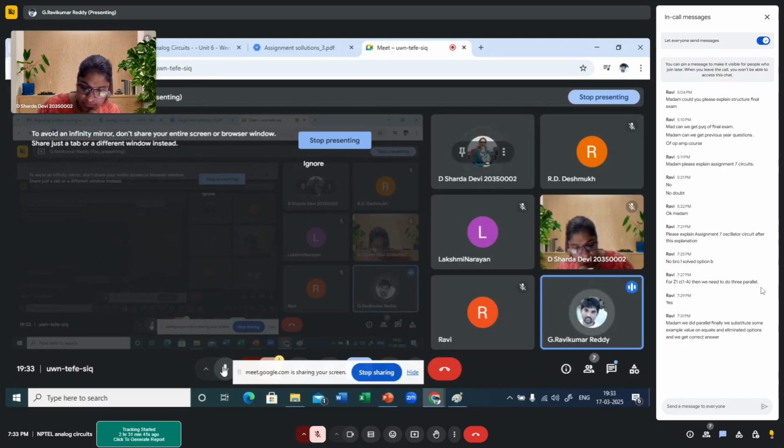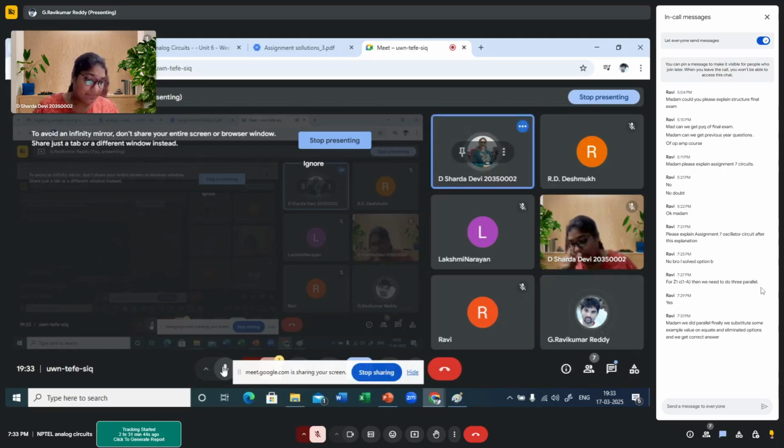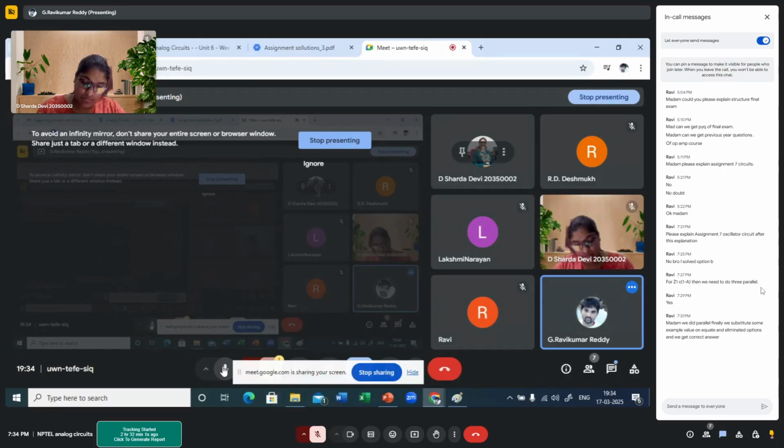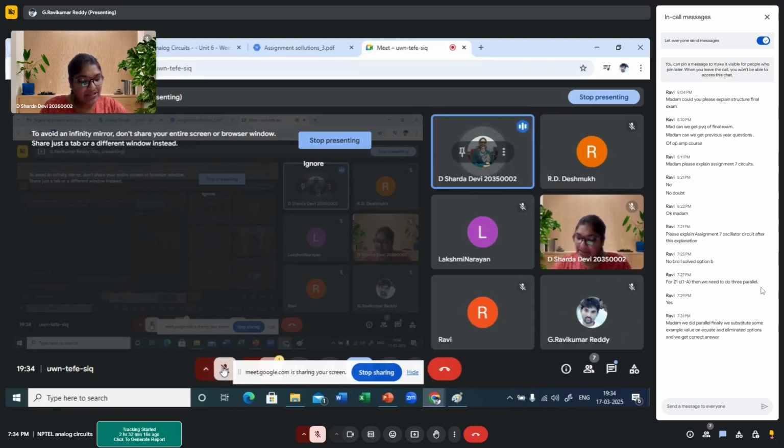There they are taking Y admittance, and at the input side they have written Y into 1 minus K. But if it's admittance, then if you make it resistance, things will change, no? In the lecture, they are taking the Y parameter, madam, and with the help of Y they wrote the equations. So if it is Y into 1 minus K at the input, and at the output side Y into 1 minus 1 by K, then if it is admittance, resistance would be opposite to that, no? 1 by that would be the resistance, no? Impedance.